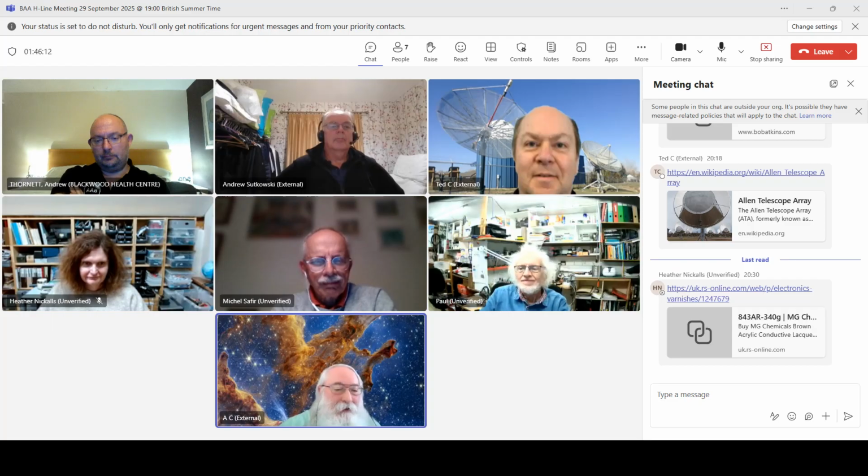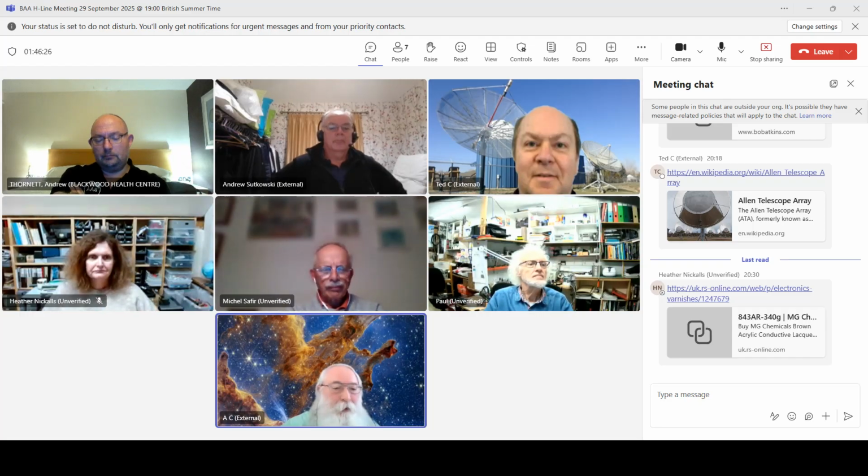It's not like a prime focus dish where you can have the full parabola and you get the intuitive sense as to where the feed would go in terms of the focal point, and that's the direction you point at. That's what you're receiving. And boy, that's just not easy at all to do with offset dishes. You have to have some other means of determining the pointing angle, as it were.